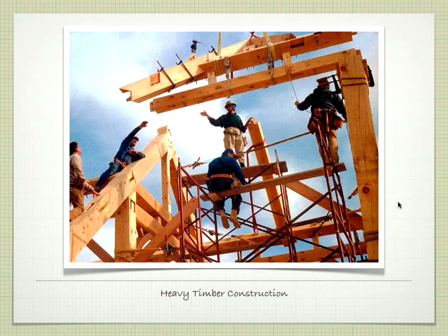Sometimes you need to tie pieces together. So we have a bent here, there's another bent over here. We need to tie them together, so this is the tie piece. Notice the fancy joinery that's done at the ends of these particular beams. This notch here is going to match up with a notch there, and they're going to slide together, and then you're going to bolt. So all this stuff has to be really carefully considered before it's put up there. If we're in light frame, you get the standard size, you put it together, you put a couple nails in it, we're good. This is a much more complex frame to build. It requires more skill, and it requires more knowledge to be able to do it. You have to learn how to do all these joints.